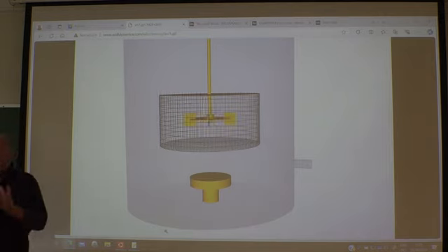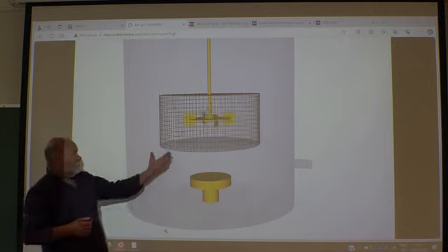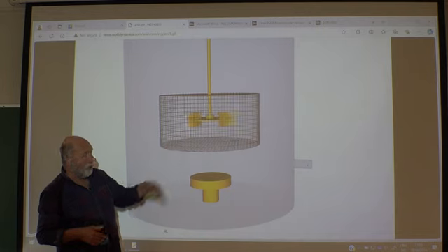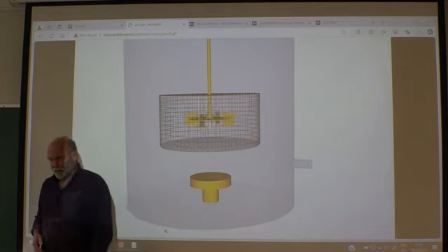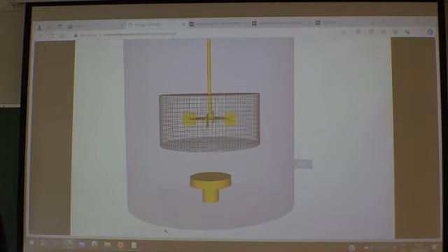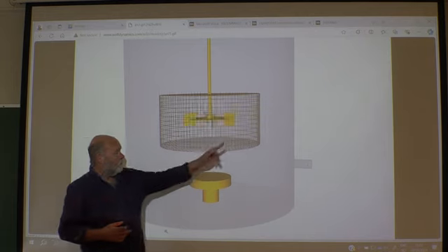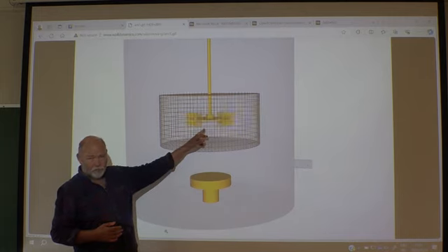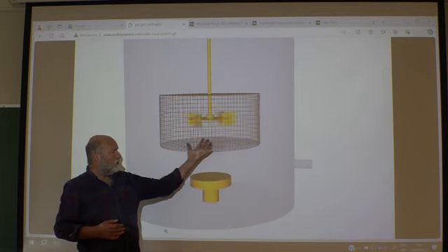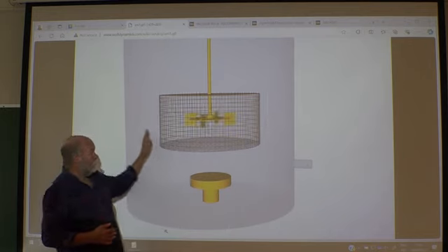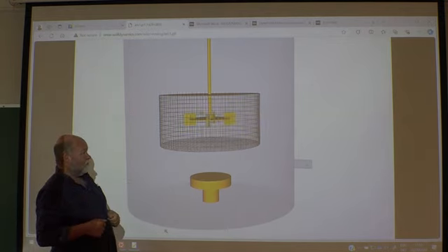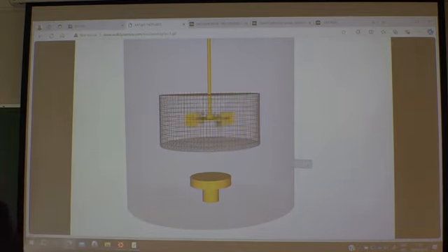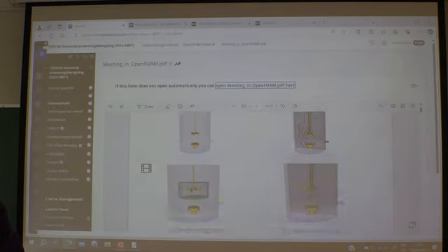So when you want to use OpenFoam, say simulating such a mixing tank where you have some baffles, some paddles that rotate, this is not easy. Then you create sort of a circular area here and mesh around these baffles, and then you let this part of the mesh rotate. That means the rest of the mesh has to be standing still, so they are sliding against each other. Tricky, but possible.